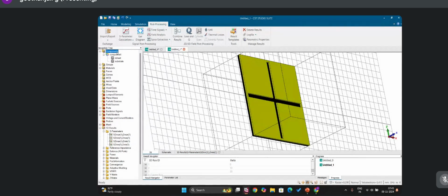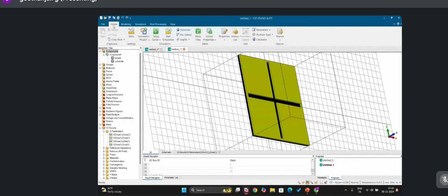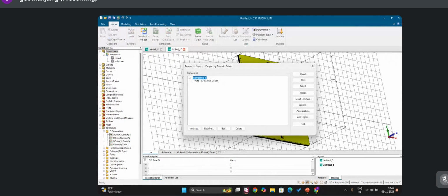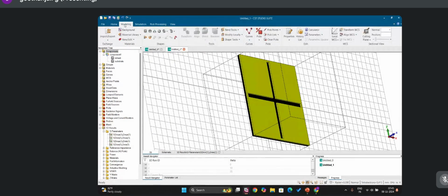And we have performed the angular stability by using the parametric sweep here. In an antenna there will be a coaxial feed or some other probe feed to design the structure. Here we are using the Floquet boundaries, because Floquet boundaries refer to the concept of periodic boundary condition, which is applied to a structure that repeats its periodicity in free space. That's why we are using the Floquet boundaries here. And so the angular stability is done.